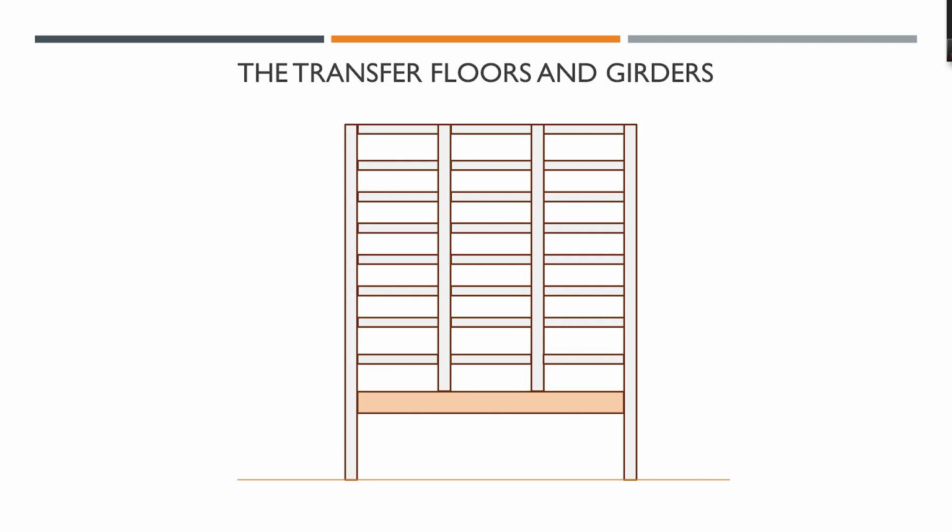So this is what I'm saying, that you disrupt the natural flow of the load by moving it to the alternate system. So this transfer girder and transfer slab will be needed here, which we will talk about in another talk. So basically, all of the gravity load coming here suddenly moves over, and this creates several problems.